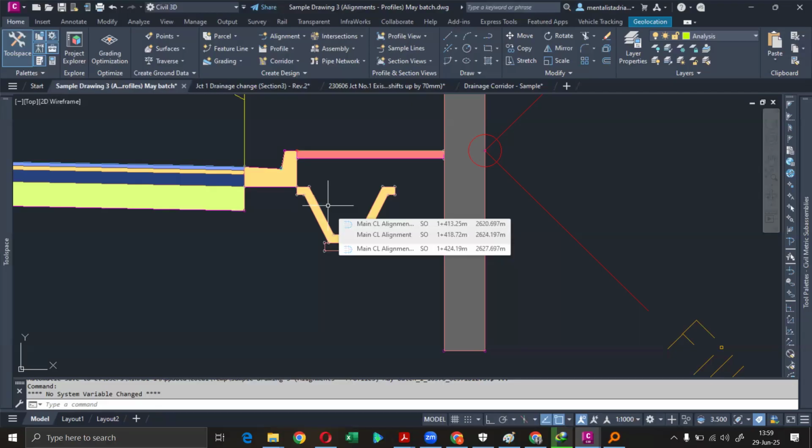Even Lugogo. You need to divert it from where it comes from, so that by the time it gets here, it's not so much. It's not that the drainage is not there. The drainage is there, and it's big. They even dug that whole big trench forward and still the place floods. So you find out that you need to look at where the water is coming from. Then you curb it, and you may find that the solution is simple.